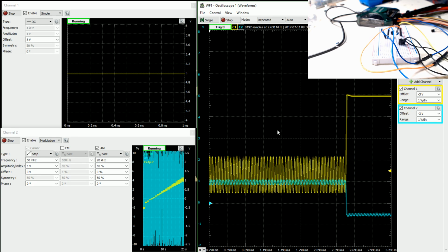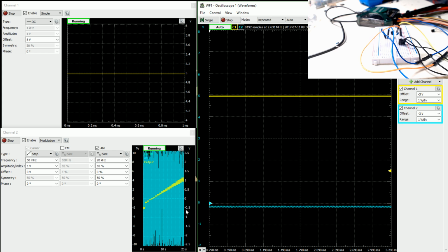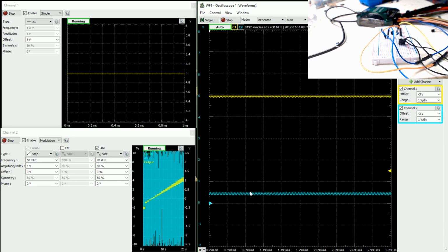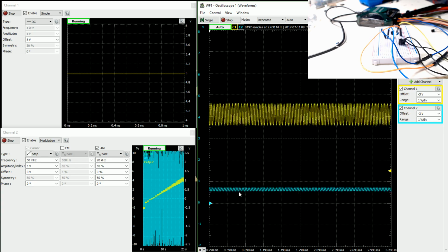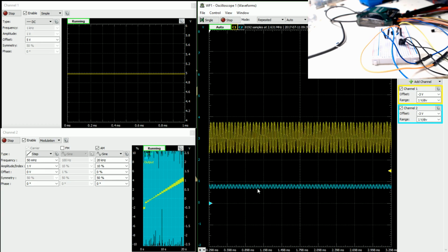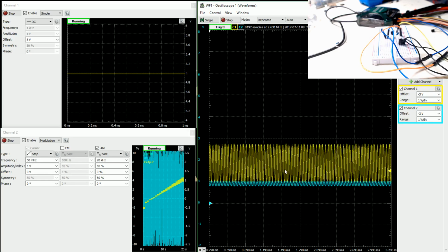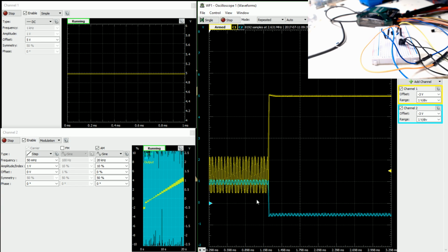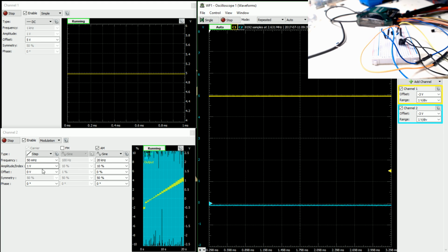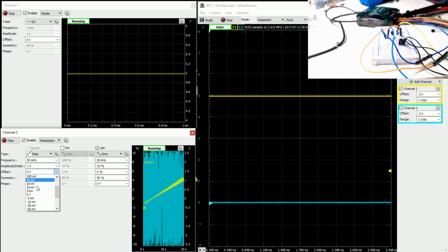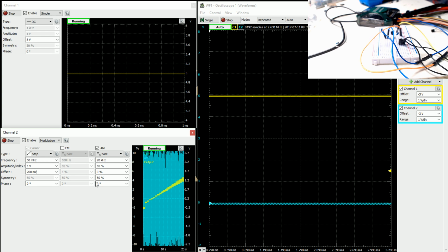And what we're really trying to show here is that as this DC value, right, as we change the bias, this DC value represents the bias from the base to the emitter. As that changes, you can actually see the amplification happening, right? What we're basically doing is readjusting the bias as we go. So I'm going to move this up a little bit here. Let's just move this up to 200 millivolts, give it a healthier starting point. So it'll go a little bit higher now.